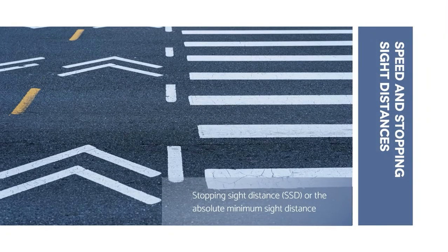Sight distance available from a point is the actual distance along the road surface over which a driver, from a specified height above the carriageway, has visibility of stationary or moving objects. The most important consideration in all these is that the driver traveling at the design speed of the highway must at all times have sufficient carriageway distance within his line of vision to allow him to stop his vehicle before colliding with a slowly moving or stationary object appearing suddenly in his own traffic lane.